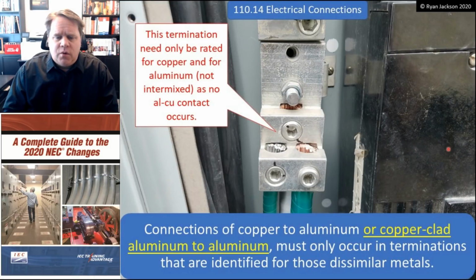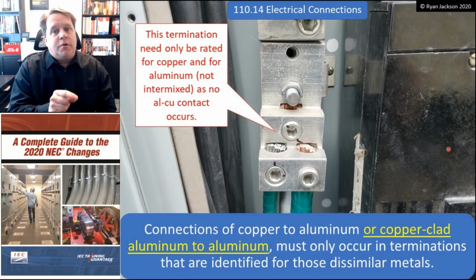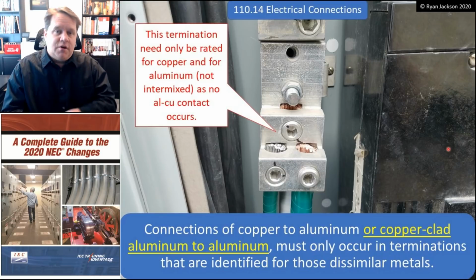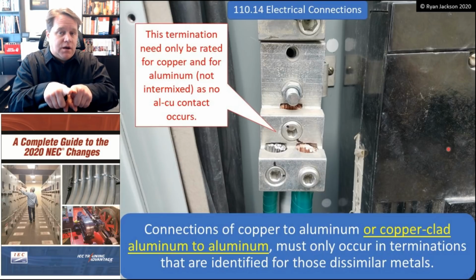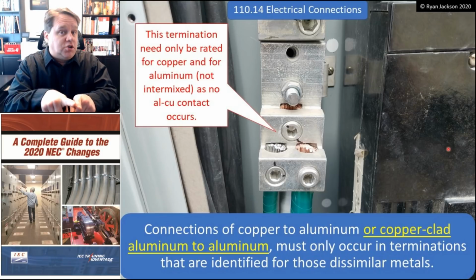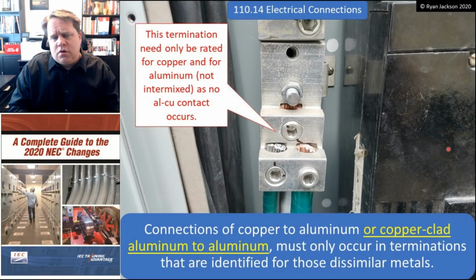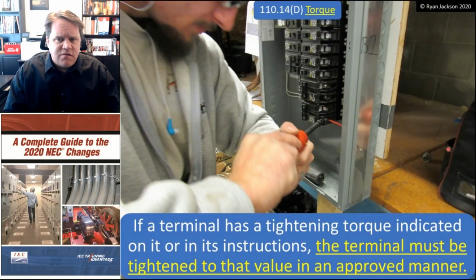And if we go back to it, connections of copper to aluminum or copper-clad aluminum to aluminum. So copper-clad touching copper is fine because that's copper touching copper. It's copper-clad aluminum touching aluminum that would be problematic. So we need to make sure that we're using the right fittings anytime we make terminations.